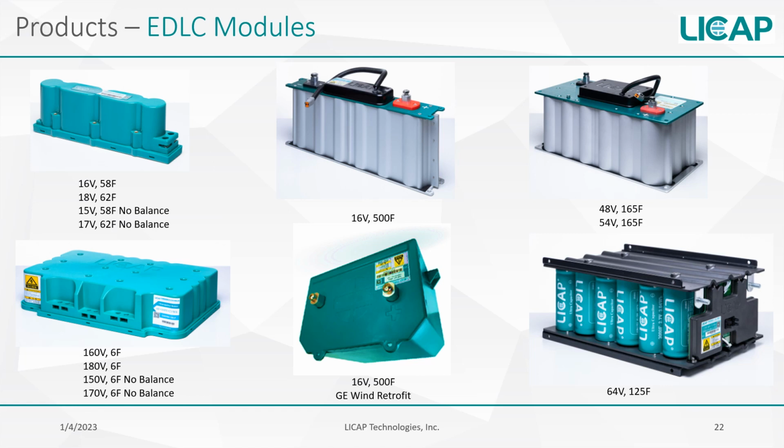In the upper right, we have a 48 volt 165 farad module that uses the 3000 farad 2.7 volt cells, and also a 54 volt 165 farad module that uses the 3000 farad 3 volt cells. And last but not least, we have a 64 volt 125 farad module that's dedicated for rack mount applications and stationary applications for the grid.